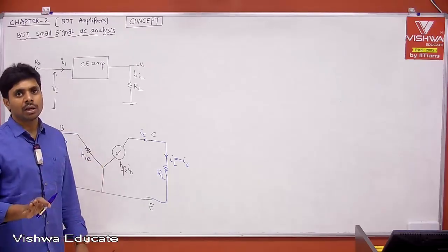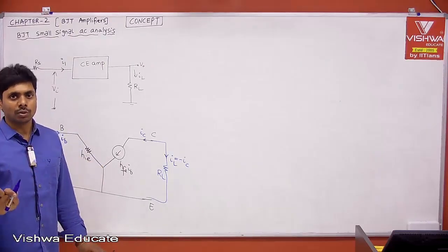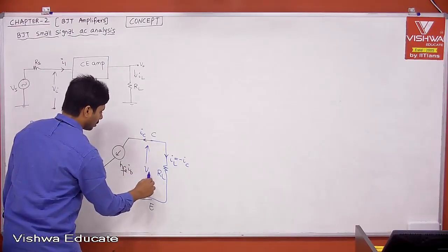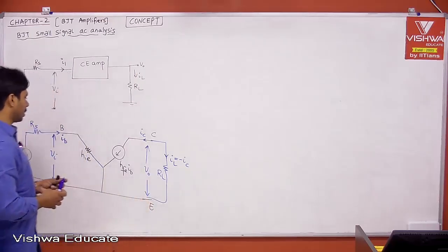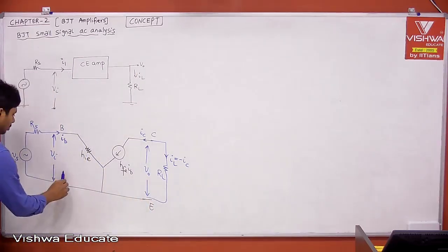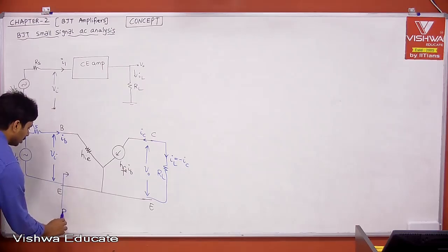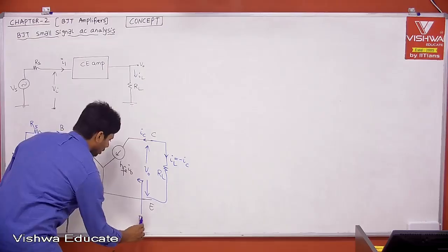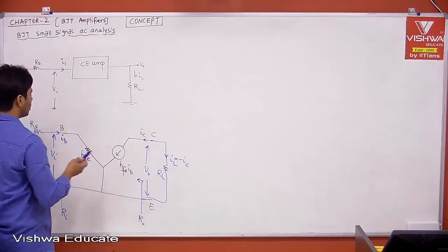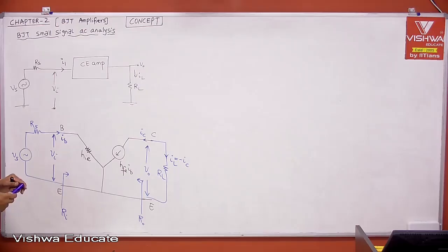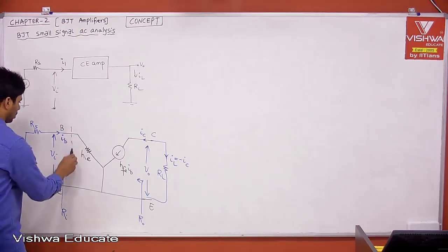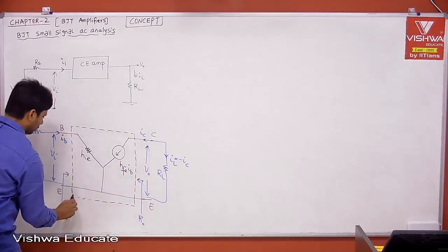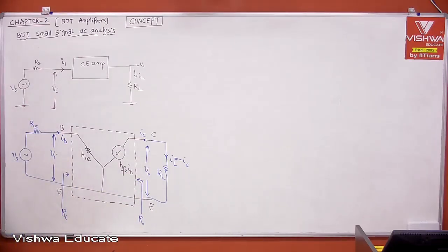Okay, we are not interested, that doesn't mean that IE is 0, no, we are just not looking into it. Therefore this is your load and this is your output voltage, let us say V0. Now it is defined with input impedance, the impedance seen into the input port of your amplifier, and output impedance. The definitions won't change, remember. But earlier it was the exact model, now it is the simplified model. Using this we need to calculate.